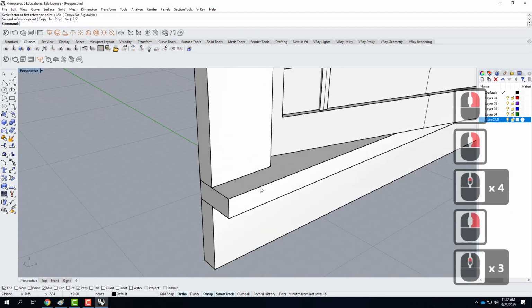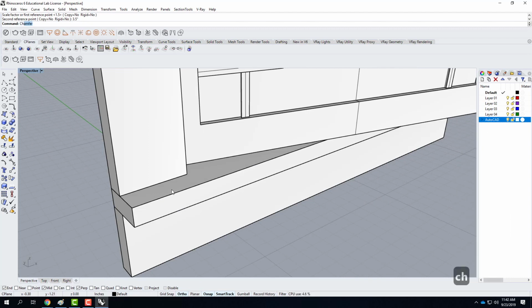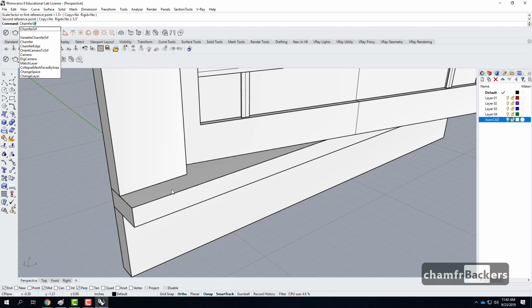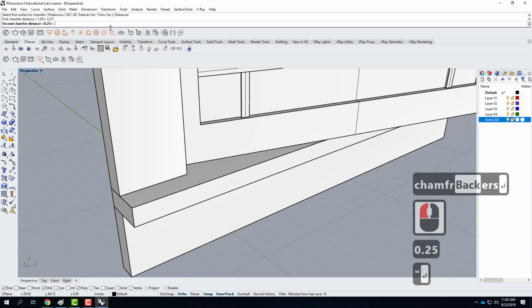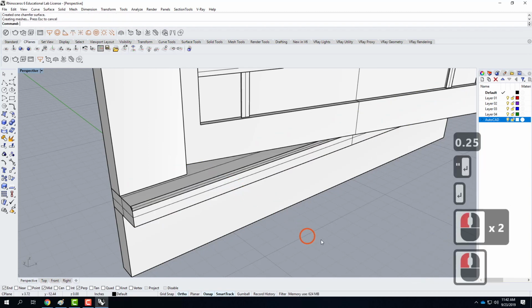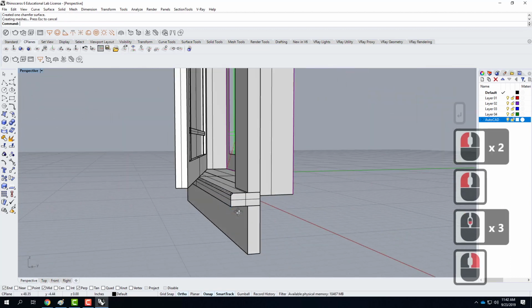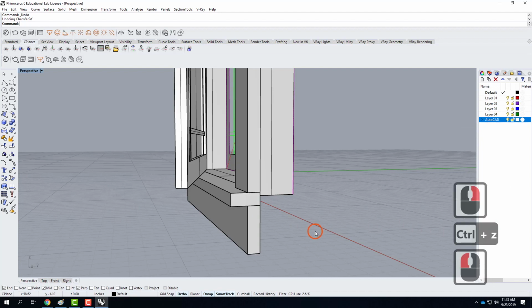You might decide that you want the edge to be tweaked a little bit. So instead of having a sharp corner, maybe you want to do that chamfer like we did with the bridge file. So I could do a chamfer surface. My distance is probably only maybe 1/4 inch or so. And I could adjust that edge should I want to. So you've got flexibility there. I'm not going to end up doing that, but you could.